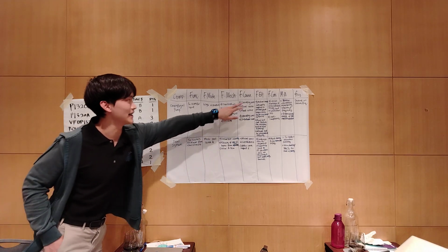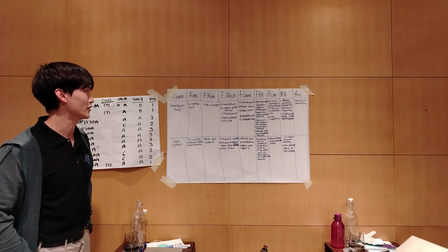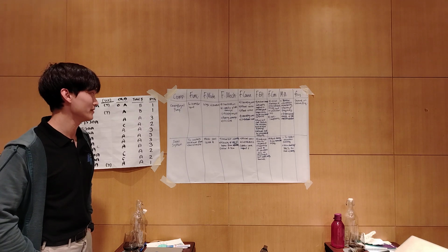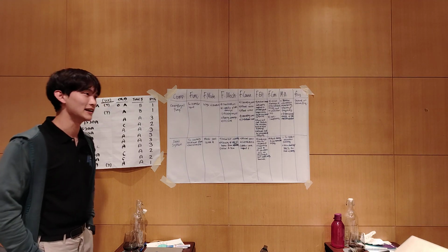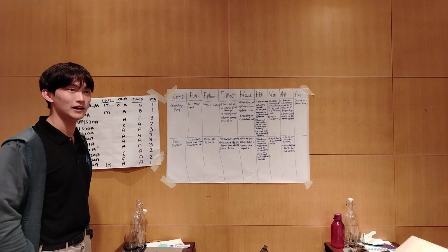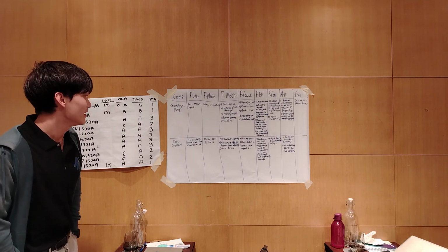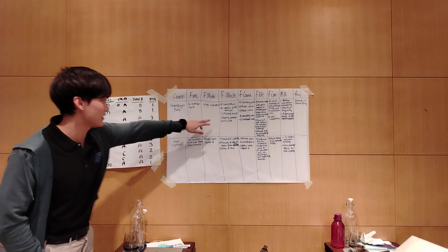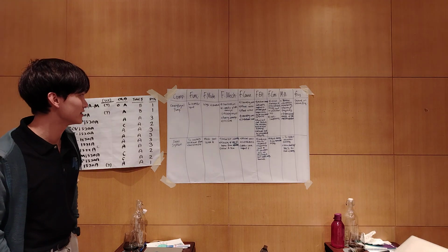So the causes for this are linked. For cavitation, the cause is operating error. We are operating outside our safe operating pressure. And impeller plate damage is maintenance error. Let's say maybe the inlet has strainers, right? So maybe for some reason the strainer was not there, and the debris managed to come into the impeller. Misalignment is also maintenance error, bearing damage is operational error, and oil leak is installation error.